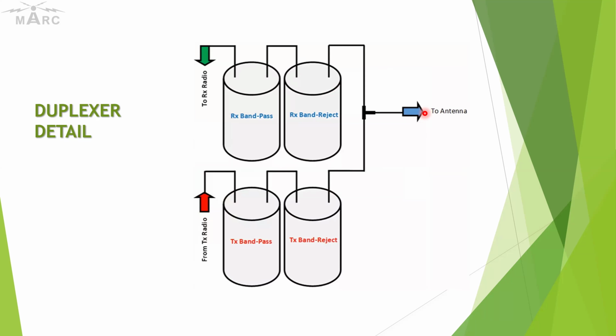Now, as we know with antennas, if you get an antenna that's cut to be resonant, then it receives that a lot better, right? But even if the antenna isn't resonant, those little RF signals sneak into the radio, and the radio has to have the ability to reject all of that stuff. So that's what these duplexers do.